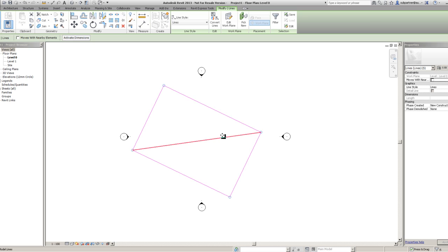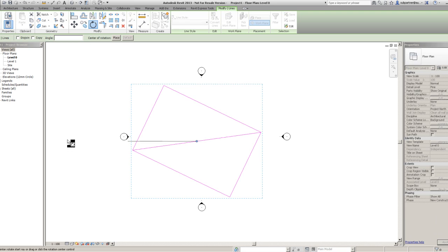What we do is this: we go rotate. Now this pivot point, this base point, isn't constrained and locked in the middle of this geometry. That's just the default of where it goes. If I hover over, you can see how my reference line disappears. That's because now I can simply left click and drag and place that anywhere I want. I just snapped it to that corner.